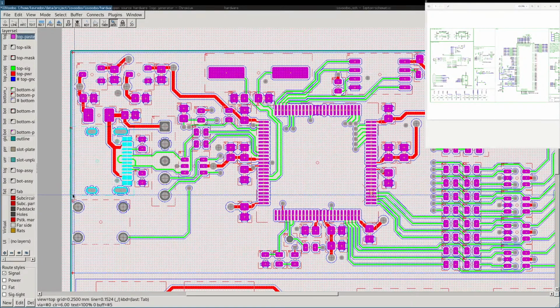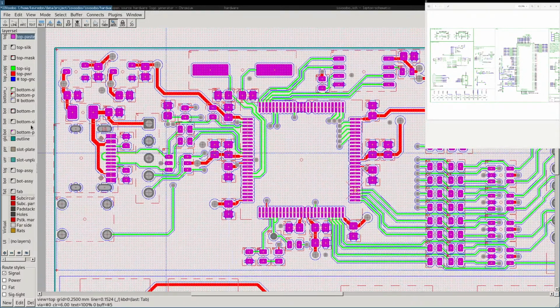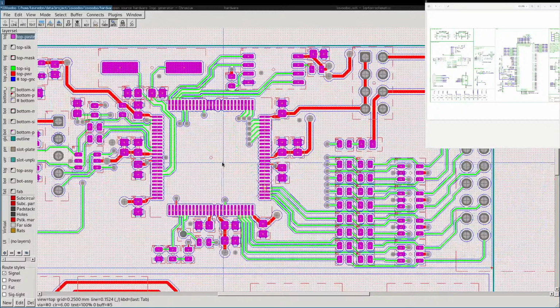Although there are some kinds of exemptions. For example, on these through holes, the connector can be surface mount soldered and you don't have to solder the through hole. I think it's called paste in hole. So I could add an opening here. This way some solder paste will be put in here, and when the connector gets there it will be soldered, and it's good enough. It's still better to solder any through-hole components by hand with the soldering iron, but it does work with solder paste for this connector, and it is also meant to be this way.